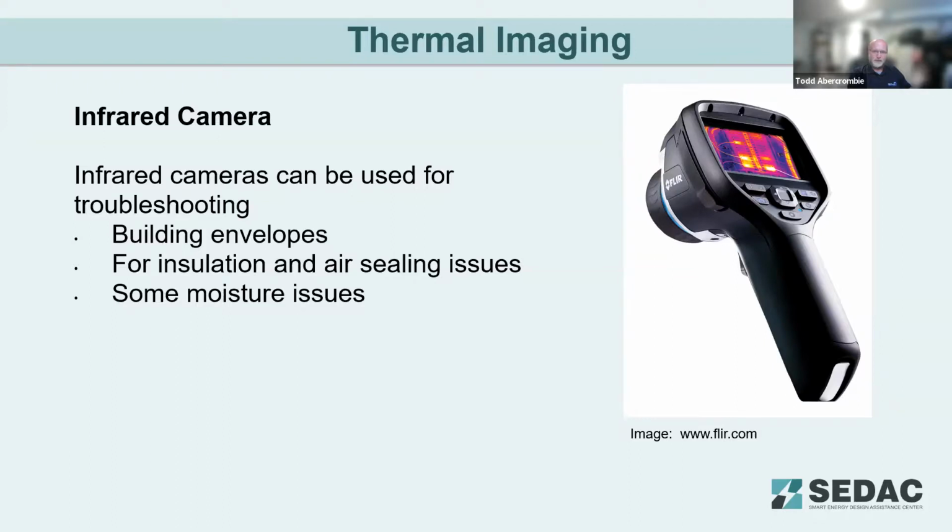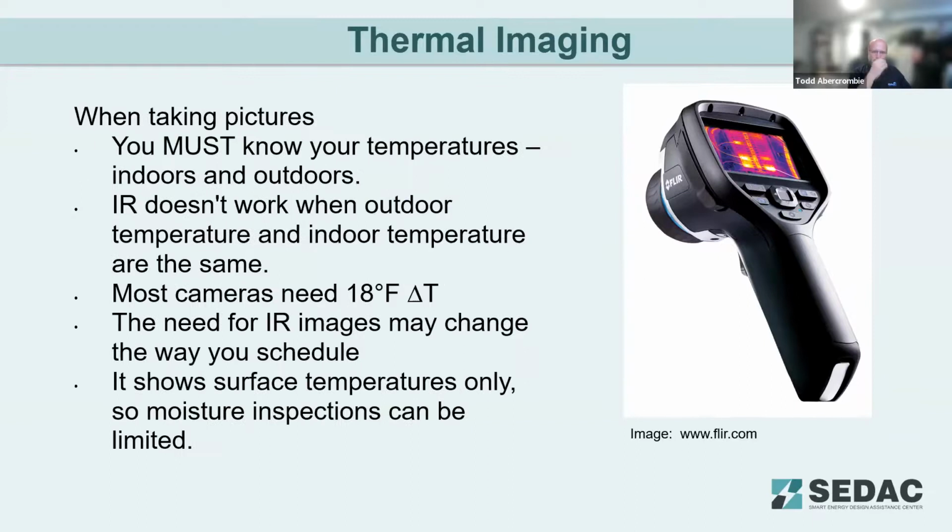I can't stress enough that you got to understand your temperature differentials as well. You can't just pick it up and see everything you want to see. And it takes a little bit of experience and training. So again, taking pictures, you have to know your temperatures indoors and outdoors. IR doesn't work when outdoor temperature and indoor temperature are the same. Need the temperature differential.